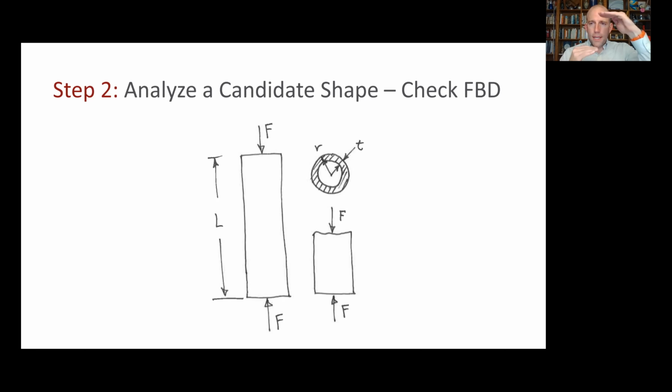But the fact that you have this axial displacement is consistent with the idea that you have an axial force, and you really don't expect much other displacement to happen. So both of those things are consistent with this candidate free body diagram. And if you were feeling unsure still, you could throw it into FEA and do a sketch analysis, but I'm feeling okay about this one.